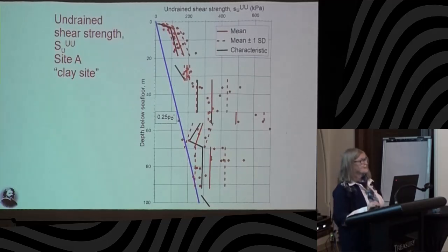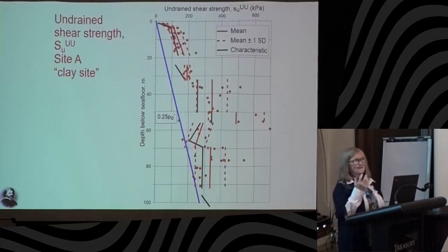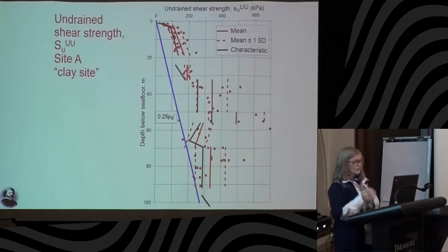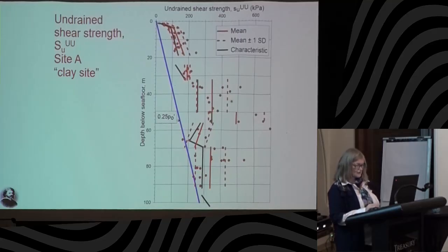And just for interest, all the data is what is in red, so there's something stronger here. But I showed you the first profile of undrained shear strength that was proposed, and this is the black line. Why this was so low, I'm not quite sure. And to me, a profile has to be logical. So why does the strength decrease by so much at this level? Okay, that was just for interest. But in the probabilistic analysis, we use a distribution like this, sometimes normal, sometimes log normal.